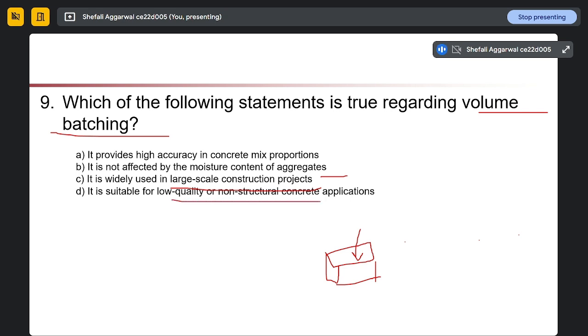So when is ettringite forming? Whenever C3A reacts with gypsum, ettringite will form. Whenever we are adding cement in water, the first compound which reacts with water is C3A. So when ettringite is forming, it is actually the pre-induction period or the initial mixing period.